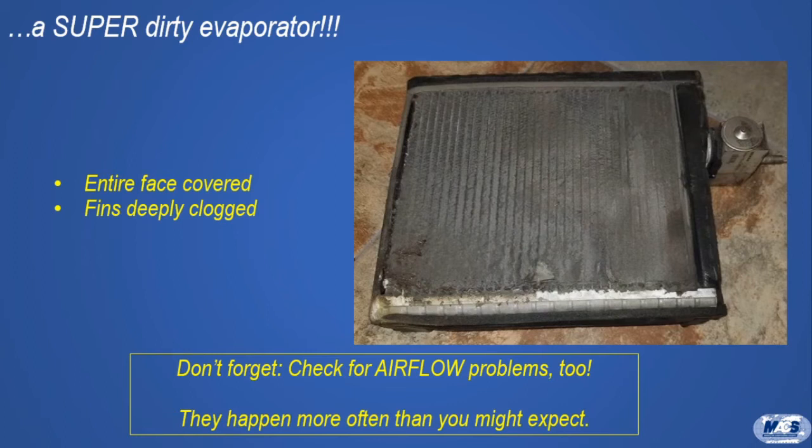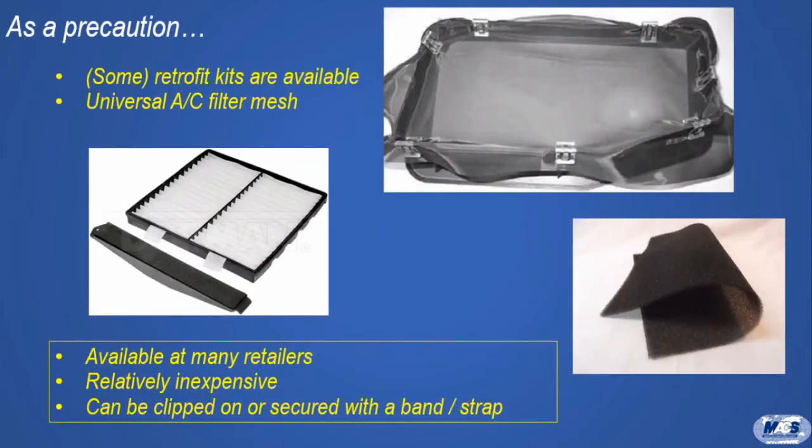And once he saw the buildup on the evaporator, he had to admit, "I should have thought of this originally." As a preventative maintenance measure, he installed a universal filter kit at the air inlet. If you have customers with vehicles used at construction sites, you'll be doing them a favor if you recommend installation of an air filter kit before a similar problem occurs.